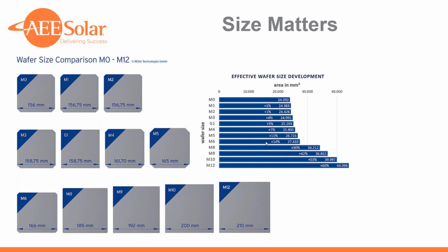The trick here, though, is that these are larger. With the same intercell spacing, you're looking at a 14% larger module. Now, a lot of manufacturers are getting around this by really squeezing those intercell margins, let's call them, trying to increase the overall, call it apparent cell sizing in a module without having a similar increase in the size of the module. If you were to not squeeze those cells in tighter, 14% is a pretty significant increase in the